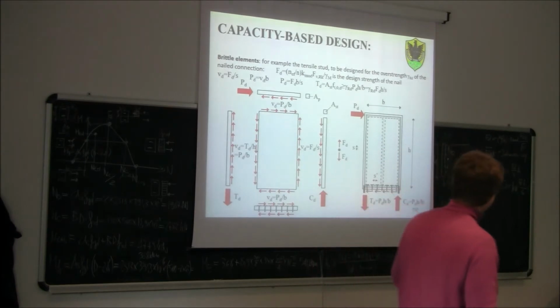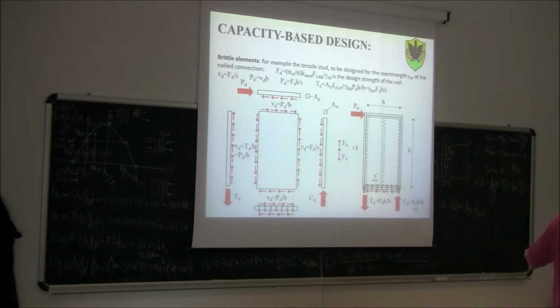And the same concept shall be applied also for the sheathing, for the plate, and for the bolts connecting the base of the plate to the foundation, for the hold-down, and also for the floors that we have above. So everything must be designed for the overstrength of the nail connection. Okay?